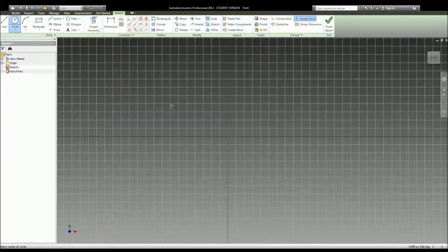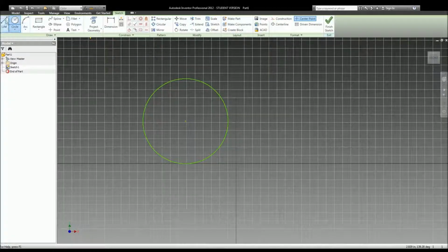It's very useful when you're playing with circles and you know that you have a chord straight across at a specific point and you only need like the big portion or maybe the smaller portion, and you can just split it and then click and delete. That of course is if you don't want to use the trim function. It's really up in the air which one is more useful than the other. I personally just enjoy using trim a lot more because it just makes everything a lot neater. It gets rid of whatever you need to split or cut away once you click on that space.